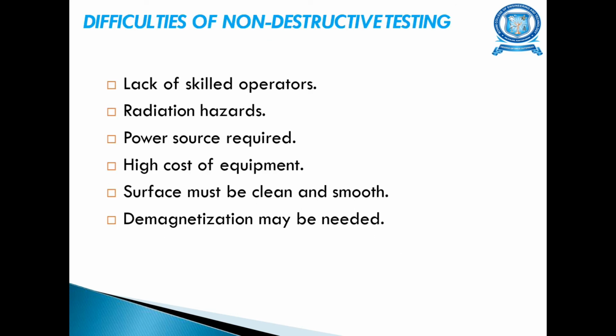And the difficulties of non-destructive testing: skilled operators may not be available. Radiation hazards are there, and the power source requirement is there, and high cost of the equipment are the difficulties of non-destructive testing methods. And the surface must be clean and smooth. Demagnetization of components in magnetic particle testing is needed.